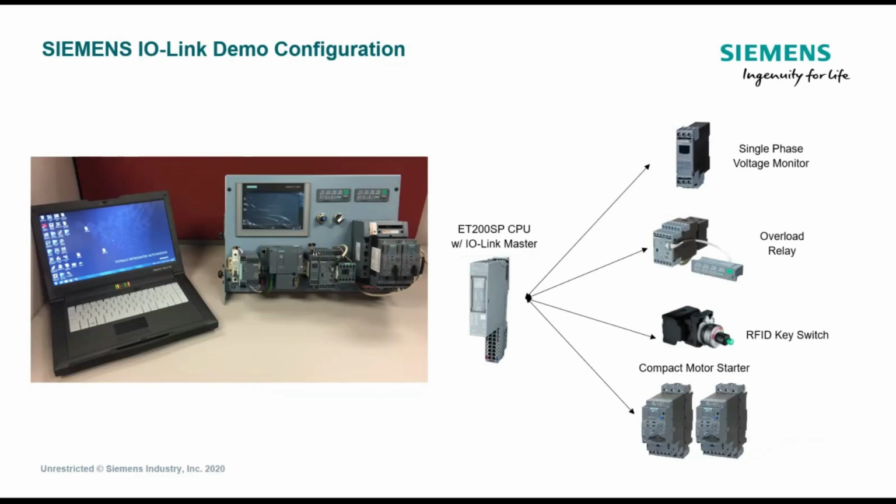So a lot of times when we promote this compact starter, not only do we promote the compact starter with IO-Link to reduce your control wiring and get better diagnostics off of the system, but we'll also marry it with our in-feed system to save you wiring and installation time for the 3-phase bus part of it as well. Also, these are kind of like a cartridge type component. If one of these was to fail, for instance, you could easily, through the slot up here with a long screwdriver, release it, and this whole starter can pull out as if a full cartridge.